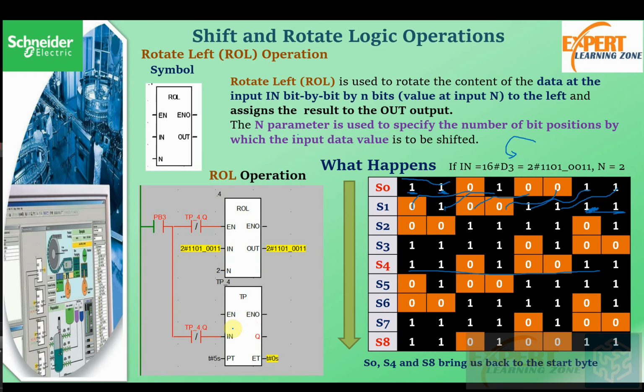After 5 seconds, the timer will come on, and the bit will be shifted. The timer is going to be shifting this bit after every 5 seconds, because after every 5 seconds this terminal is going to go low for this timer. So after 5 seconds it goes low and up again, and then shifting will constantly be taking place.